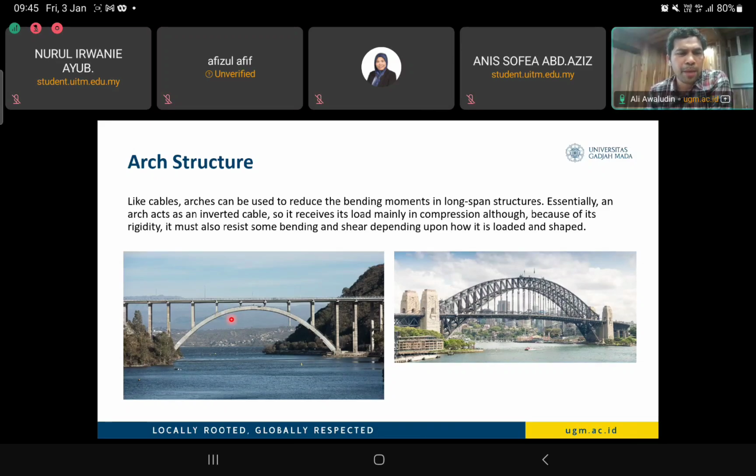So we have the vertical member here transferring the load from the deck to the arch system, and then from the arch to the foundation. So this is also another efficient structure. We will see in these cases that the arch system will experience completely compression, in contrast with the cable system. The cable system experiences tension forces,